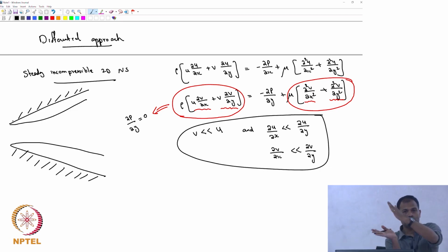Let's say we have two plates, diverging, and there is a fluid coming, and the boundary layer starts growing on the solid wall. Because fluid is going inside a diverging channel, what happens to the velocity? Velocity will decrease, right? So that would mean pressure would increase.